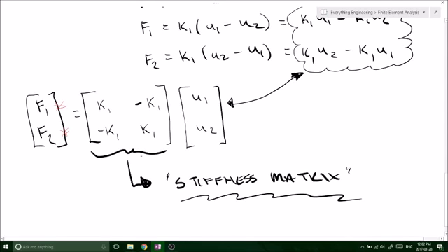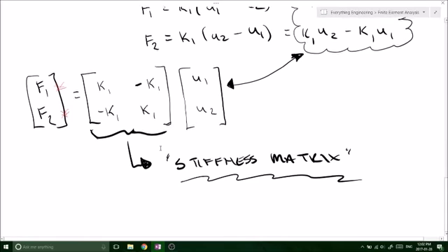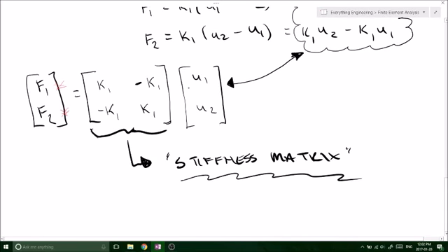So basically now we've derived the stiffness matrix in one-dimensional analysis. And this can be applied now to multiple nodes in one-dimensional forces. And I will be doing an example following this video where we'll be looking at two different cross-sections and an applied force and two fixed ends.